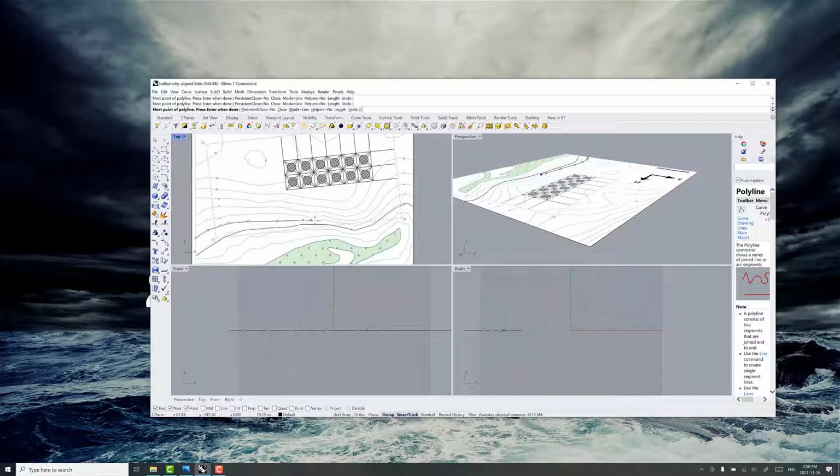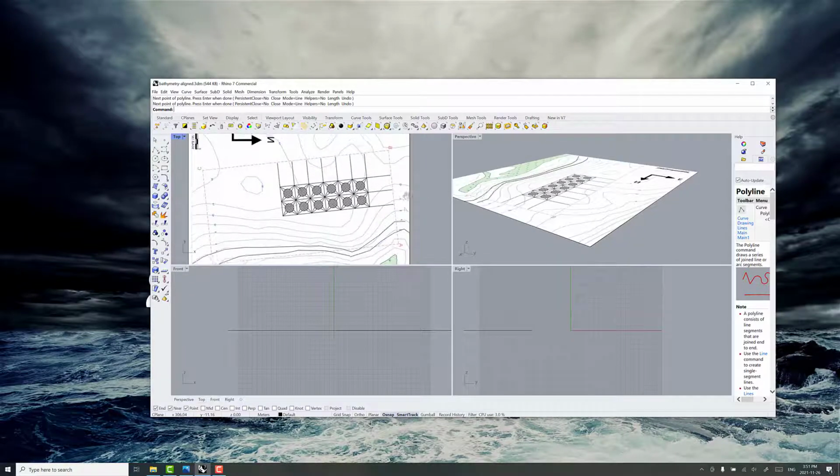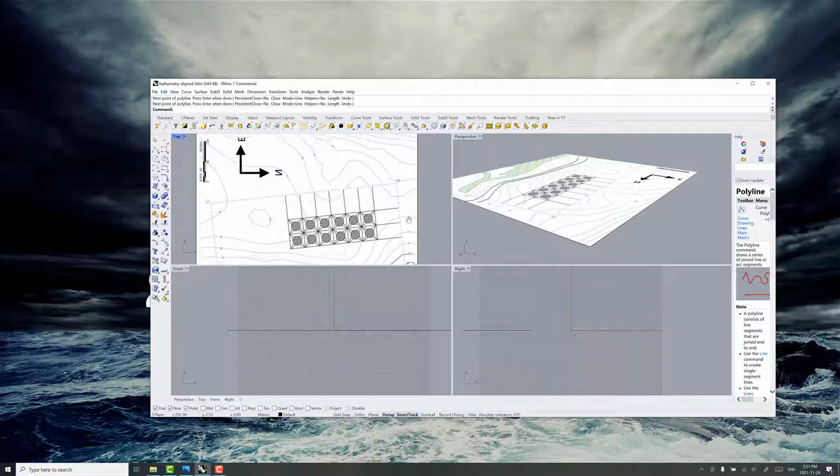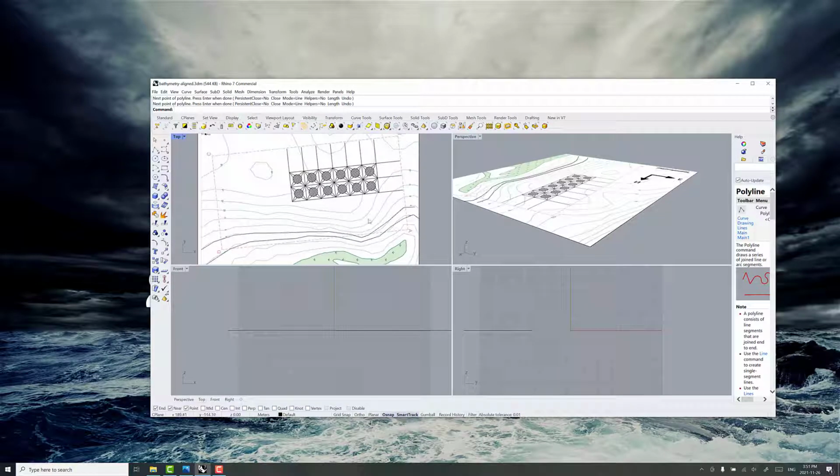This is the 4 meter depth contour line here. You just do Control Z if OSnap's causing a little bit of trouble there. And we're going to continue on drawing the depth contours and adjusting the height shortly.